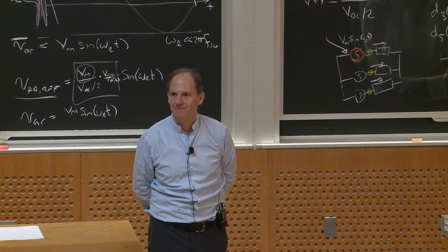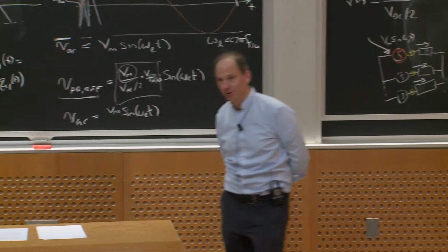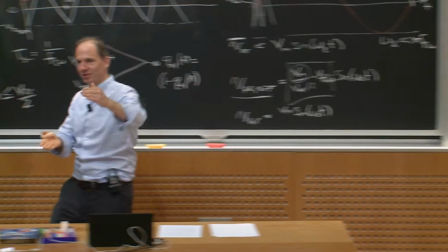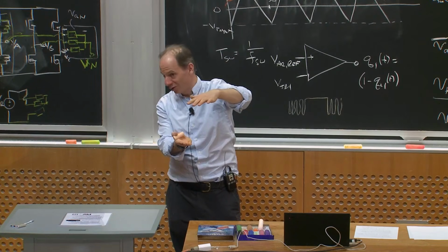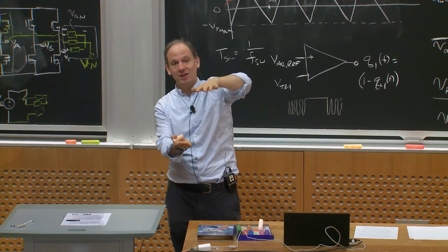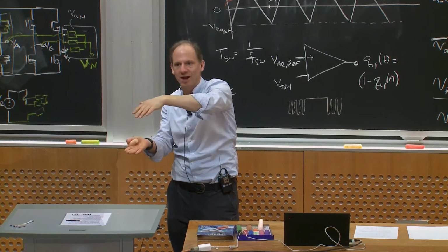Is it possible to step up VDC with a boost stage before? Absolutely, and in fact that's what people do. So why is this a concern? Because if you're in a Prius, you have this bus voltage, which is your battery voltage, and that might vary over some range, and you're trying to drive this motor whose back EMF varies over some range.